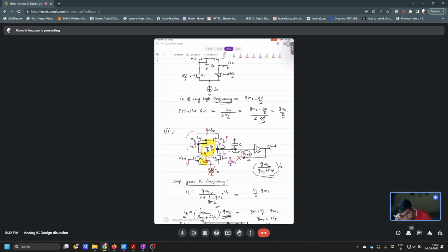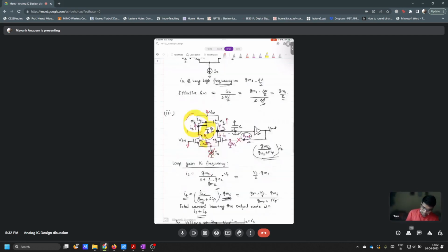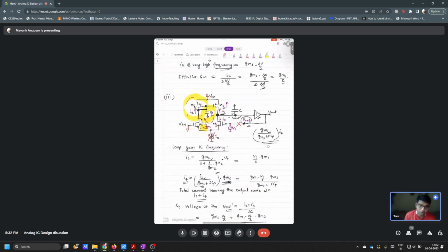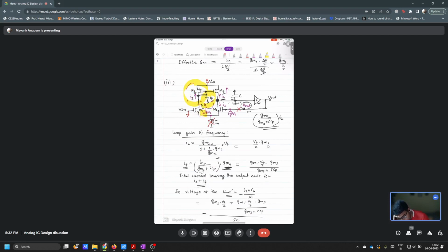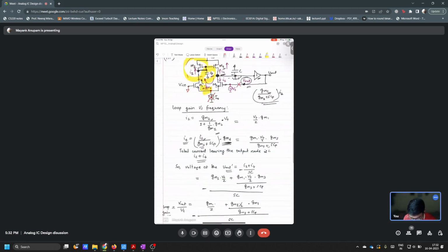It's a diode connection here, right? And that is also not infinity, right? So that is why the looking-in impedance here will be 1 over Gm1. It can be approximately equal to 1 over Gm. Fine.